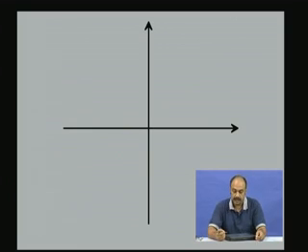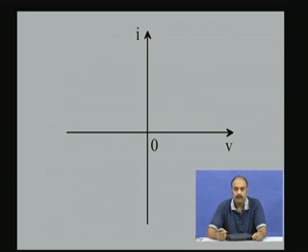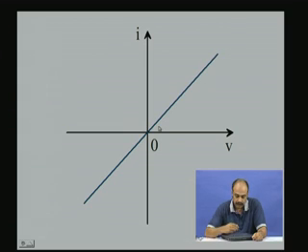So, let us try to characterize the resistors. In fact, most of the components generally we characterize by the IV characteristic. We put the V voltage on the x axis, I on the y axis. So, here in this particular diagram, V is the independent axis and I is the dependent axis. So, in this IV characteristic, the character of the resistor, as you see here, is a straight line, and the slope in this case, I by V, is 1 by R or 1 by the resistance value. So, this is how the resistance is described.